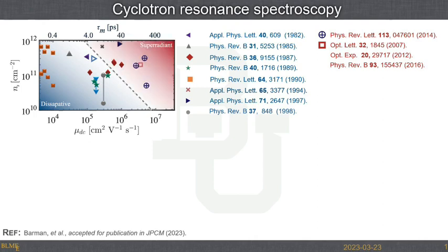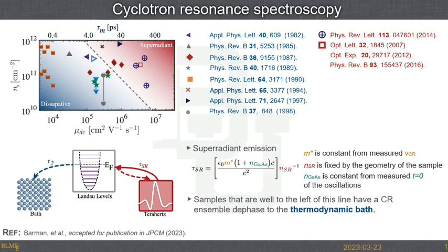And what we've been able to do now is look at higher and higher mobilities. Currently, the highest quality samples are somewhere in this 10 to the 7th region. That's looking at materials where there are very few defects, very few dislocations. It's an extremely high quality material. I'm able to put an electron into some sort of superposition state and it's going to stay there for a long period of time, the so-called coherence time.